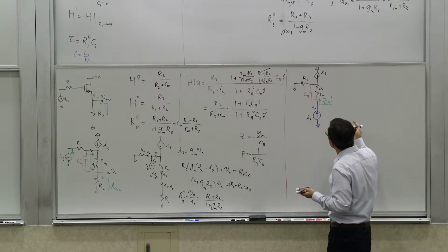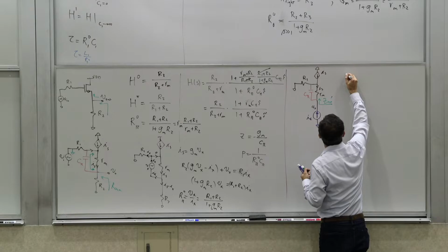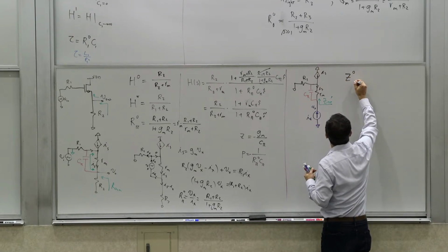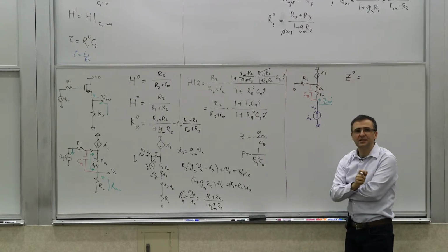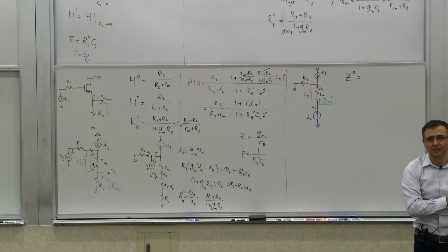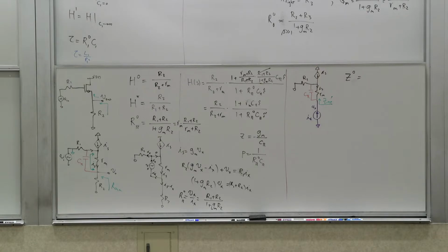So what are we calculating? Let's find out. There are three things we need to calculate, like any transfer function, right? We need the Z0, not Z pi 0, sorry. Z0. What is Z0? It's the output impedance when the element is zero valued, meaning the capacitor is open circuited, right? What do you see looking into this when the capacitor is not there, essentially? What is the output impedance when the capacitor is not seen? If it's a MOSFET, what would you see? Do you see the effect of R1 at all? No, right? Because that current is zero.